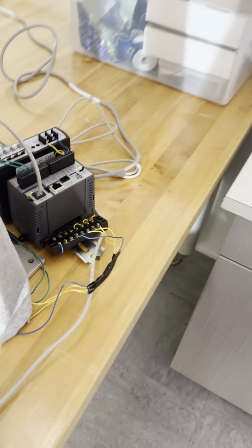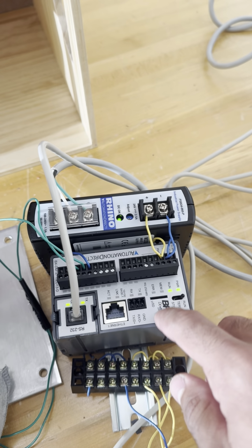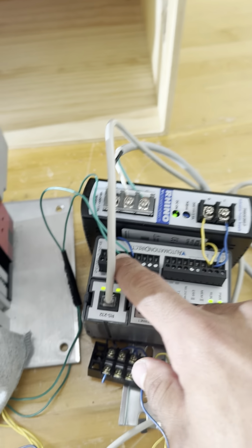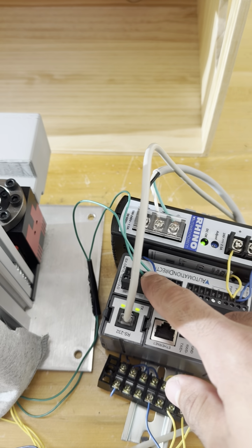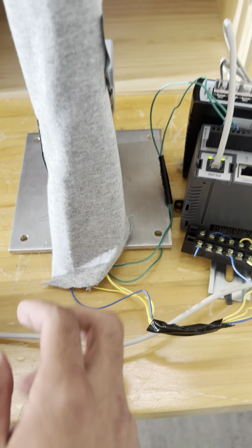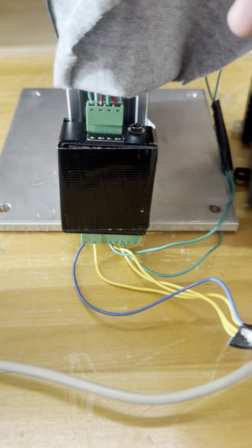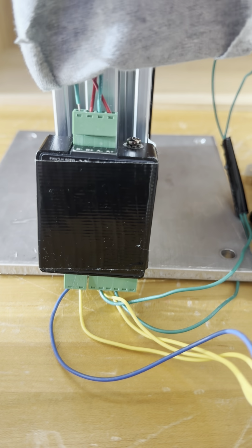Now we go over here, our PLC setup. Here's our bus. On the PLC, we only have two outputs to the actual stepper drive, Y0 and Y1, which are step minus and direction minus. These control the direction and the number of pulses that are sent to the step motor. Here's our stepper drive wired in the back here.